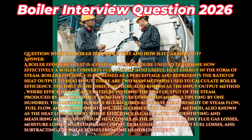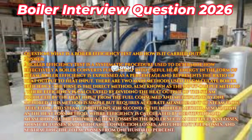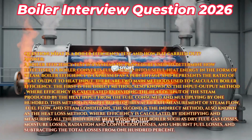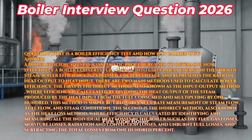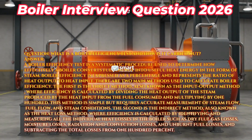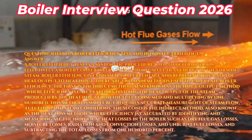The first is the direct method, also known as the input-output method, where efficiency is calculated by dividing the heat output of the steam produced by the heat input from the fuel consumed and multiplying by 100. This method is simple but requires accurate measurement of steam flow, fuel flow, and steam conditions.